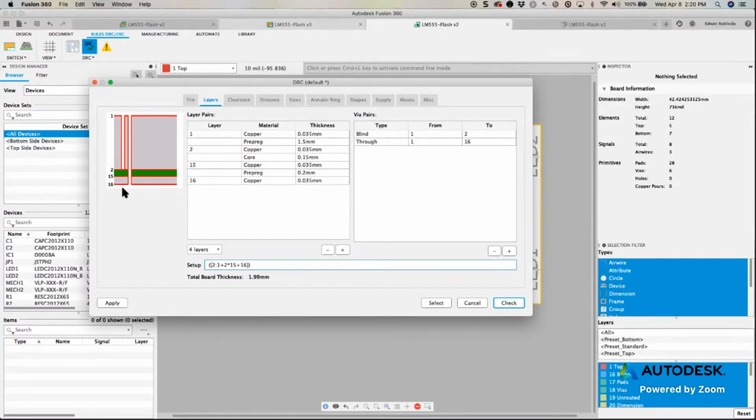And the key advantage is that you're saving space, because wherever you have a hole, that's an area that makes it more difficult to place any type of components. So in really, really dense layouts, these end up saving real estate on one side of the board. That's their big claim to fame. They are more expensive to produce, so it's not something you want to use willy-nilly. You really want to make sure that you have no other option but to use a blind via, because they increase the amount of time it takes a board to be manufactured. Remember we were talking about that sandwich process?